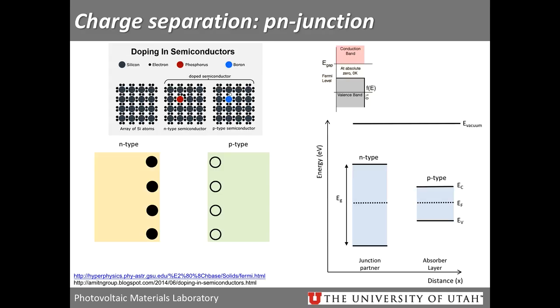Okay. So as we add atoms, impurities, or dopants, if we look at silicon and add a phosphorus atom, that is a group 5 element, so it has an extra valence electron, we essentially add an excess of electrons, and we can dope silicon N-type, which just means that you have extra free electrons.